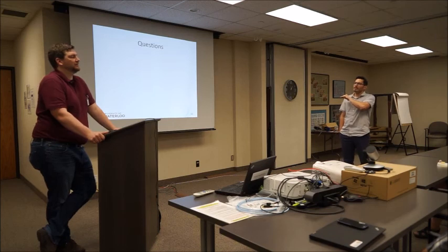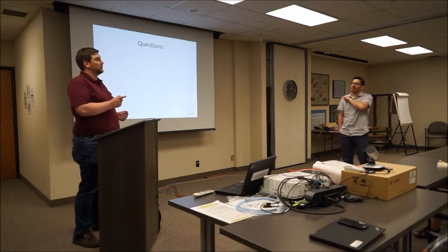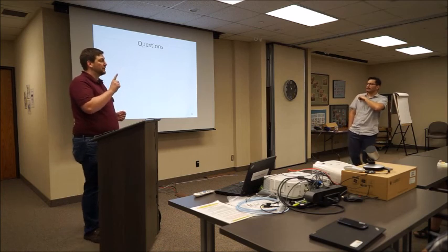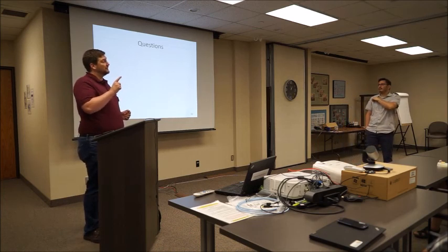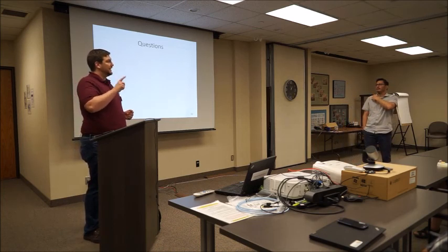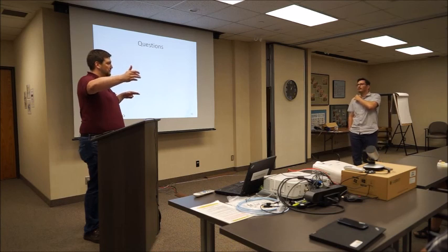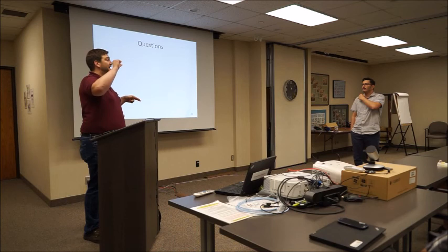We might have to take this elsewhere because I'm not sure if I entirely get your point. There's two things. In the talk I was discussing the use of effective parameter models. So that's different. The effective parameter, this is the danger of what I'm talking about. For example, you can't directly apply the Darcy-Buckingham law on a heterogeneous surface to determine the average flux through a plane that's heterogeneous and use even an effective saturated hydraulic conductivity.